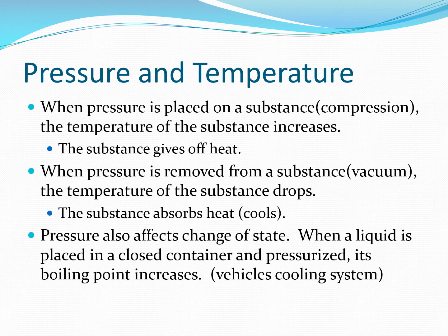Pressure also affects change of state. When a liquid is placed into a closed container and pressurized, its boiling point increases. That's the example I just gave you with the vehicle's cooling system. But let me give you another example. Think about a can of propane. Some of you, probably a lot of you, have used a barbecue grill at some point in time. Well, we use a can of propane to do that. Back in the days when we didn't have overfill protection devices on that propane valve, you would open up that valve, and what do you get out of it? Well, it's going to come out in a state of vapor.